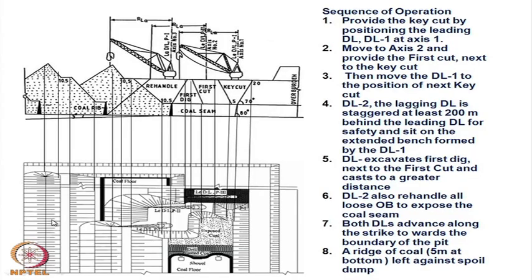So, you can combine these two. If you know how to draw the balancing diagram, from there you can draw the plan view. So, here the construction lines are shown. You can see that this is your original bench, in this slope. This is the high wall. Now, here you are giving a box cut, this key cut material. You can see that after giving the key cut, this face is created.